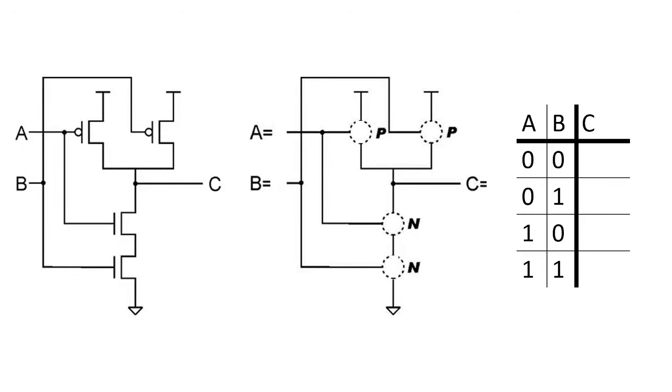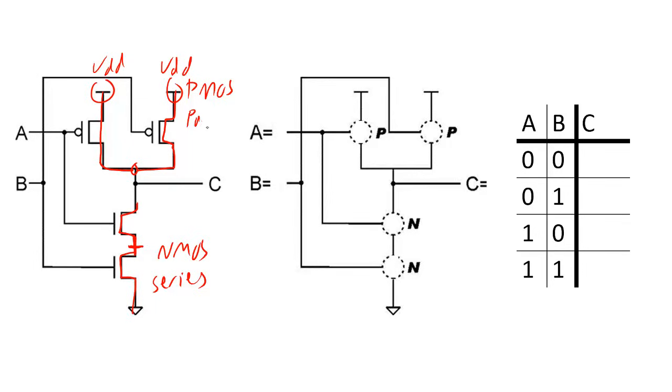When we build more complicated digital logic circuits, it becomes important to notice there's another part of what makes these complementary. Down here, NMOS transistors are connected in series. That means the output of one is connected to the terminal of the other. Whereas our PMOS up here are connected in parallel, where both of their outputs are connected together, and they're both connected on their terminals to VDD. And these differing paths, this parallel path versus series path, is really important. Anytime you have a PMOS in parallel, you need to have an NMOS in series. If you have a PMOS in series, you need to have an NMOS in parallel. And that's how we build our logic gates, so that we maintain this complementary functionality.